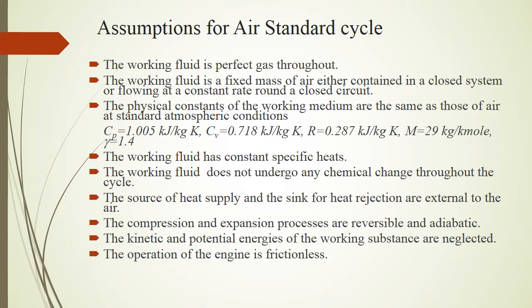Air standard cycles are cycles that use an ideal gas as the working substance or working medium. Air is assumed to be the working fluid in the internal combustion engine, and as you all know, air behaves like a perfect gas, an ideal gas.